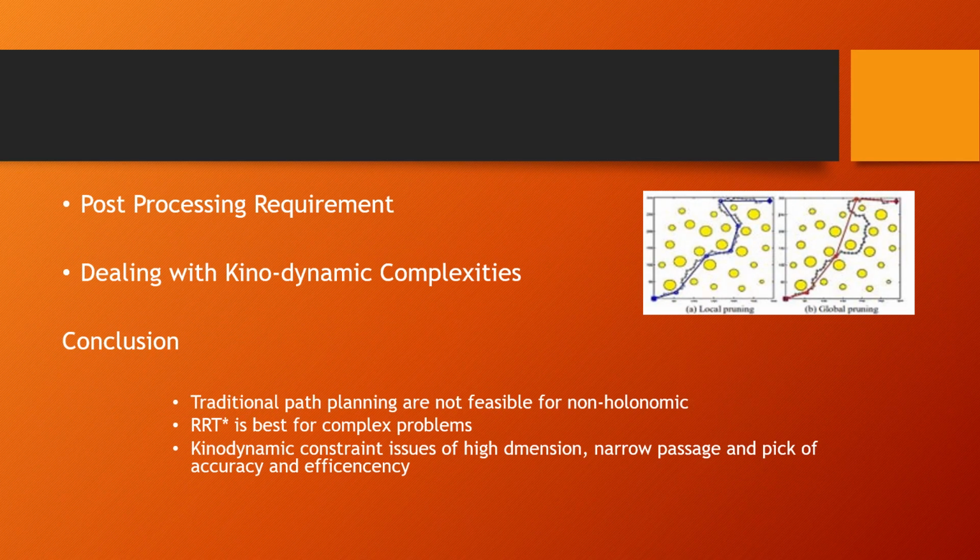With post-processing requirements, two common types of pruning, both local and global, are shown. In the case of UAVs and car-like robots, pruning generates a linear piecewise function, which is not feasible for them. To resolve this, in the RRT star variants discussed above, spline methodology using Bezier was discussed, but these too have limitations in maintaining continuity using a suitable degree of curve. In non-holonomic and kinodynamic constraints, after trajectory generation, the complexity of planning of the search space is expensive. Considering the robot's orientation in the state vector increases the complexity of the configuration space, making it challenging for motion planning RRT star applications.